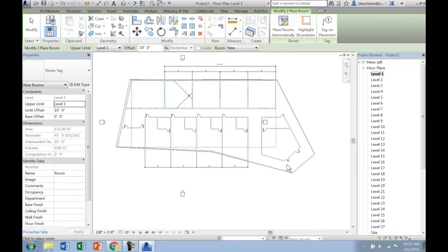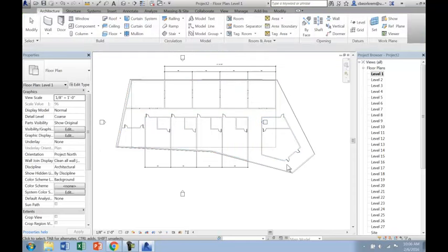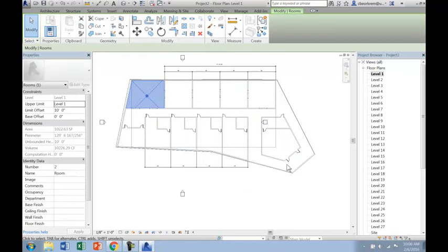You can see by default when I go to an interior space here, it's actually seeing the boundaries of each of the different spaces and articulating them. So what I want to do is come in, just click through and define each of these as a separate space. You can see how here in the corridor it actually doesn't see an enclosure, so it's not delimiting it for me. Each of the artists in residence, and then each of the closets that are associated with it, the storage for the retail, and the retail space itself. Once those are all done, you can see as I mouse over that I get that X, and I can select it.